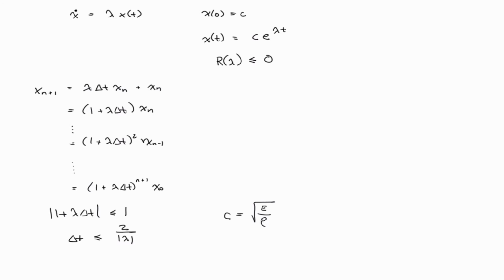So while it's great to have a method that's so easy to implement, for very few scenarios is it really useful. It turns out that one of the useful scenarios, that I used to work in that area, is impact. So in car crash, in penetration mechanics, where the entire event may only be 6 milliseconds, then this is the method of choice because it's very robust and it's fast.